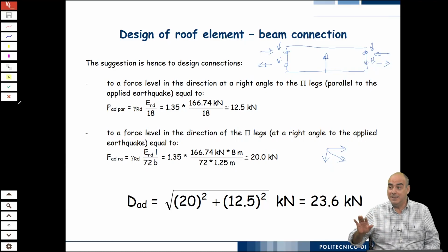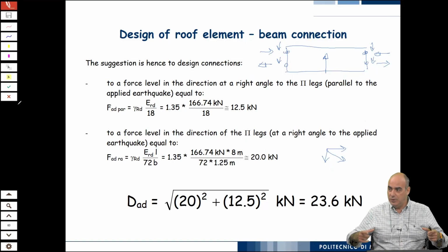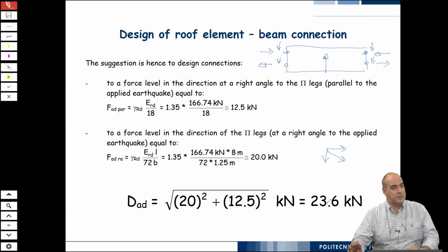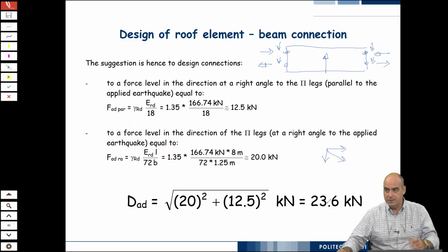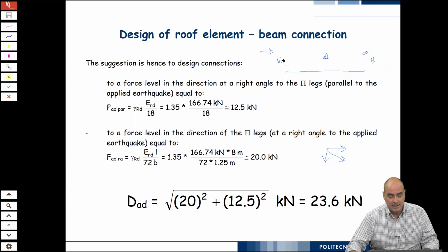So the lateral chord action is also demanded of these connections. You see, this is a force which goes on a single dowel, so you are requiring this dowel to take more than 2 tons and so on. So it can be a huge demand. You just rely upon these dry connections.